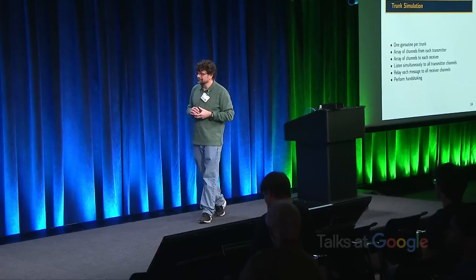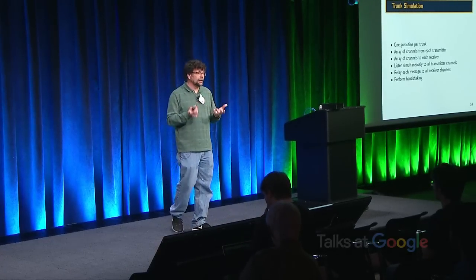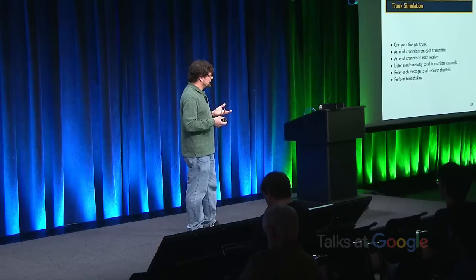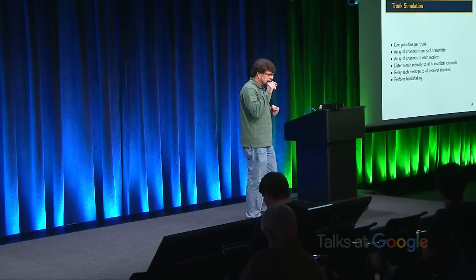So I swallowed hard and said, okay, I'll go ahead and implement a handshaking mechanism. So the idea is that if I receive a clock signal, I'm not going to send back the acknowledgement until I have finished with anything I'm sending and gotten the acknowledgements for those. And then I'll be able to send my acknowledgement back.